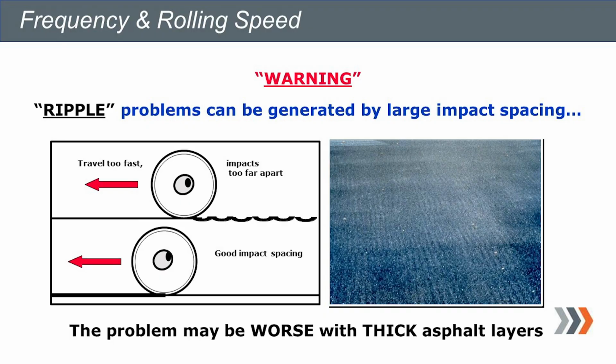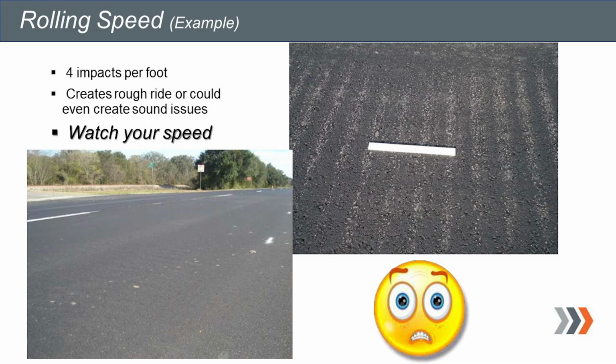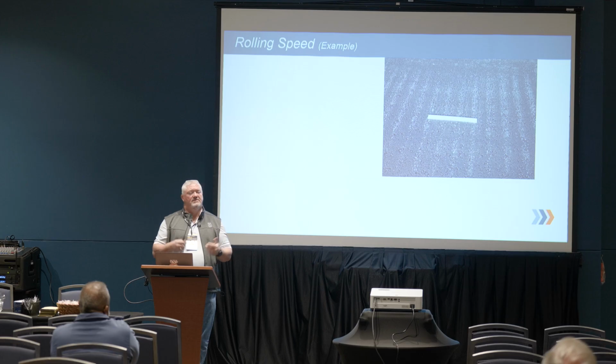We don't want to see this, whether it be we're vibrating on too cold a material to build a chatter and start crushing rock, or we're spacing too far and having issues like that. This is an example of a project I was called on down in Georgia where a customer was using one of our oscillation rollers, and they said every time they used our oscillation roller as a finish roller, the road had a hum in it. Never heard of a singing road, but okay, we'll go down and check it out.